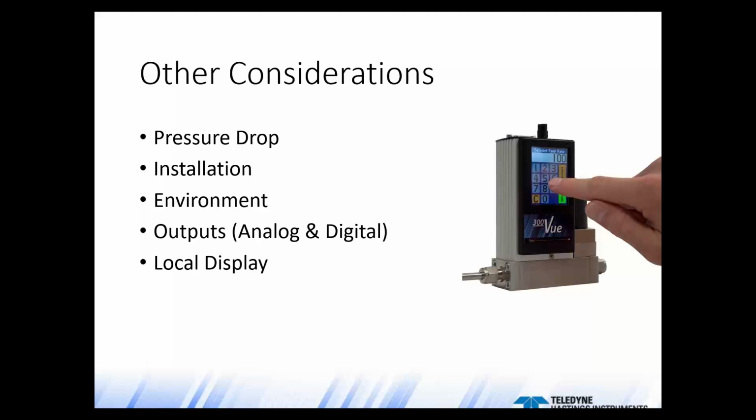Some of our flow meters have sintered elements to set up flow into the meter, and those sintered elements also act as a filter to keep out contamination. So these are going to have a higher differential pressure, a higher pressure drop. So you might want to talk to us. We'll give you some options and discuss the pluses and minuses of each.